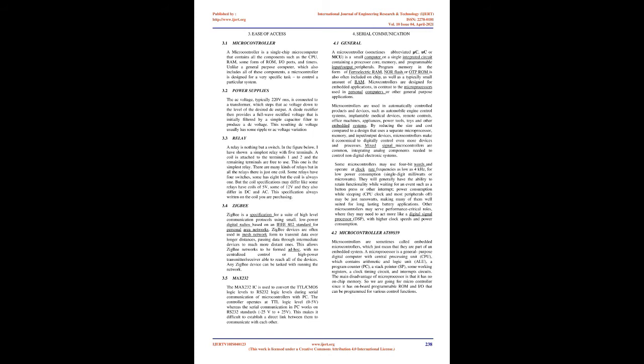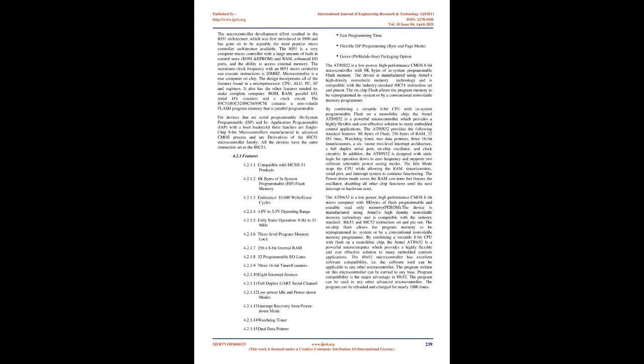The microcontroller development effort resulted in the 8051 architecture, which was first introduced in 1980 and has gone on to be arguably the most popular microcontroller architecture available. The 8051 is a very complete microcontroller with a large amount of built-in control store, ROM and EPROM, and RAM, enhanced I/O ports, and the ability to access external memory. The maximum clock frequency at which an 8051 microcontroller can execute instructions is 20 MHz. Microcontroller is a true computer on chip.